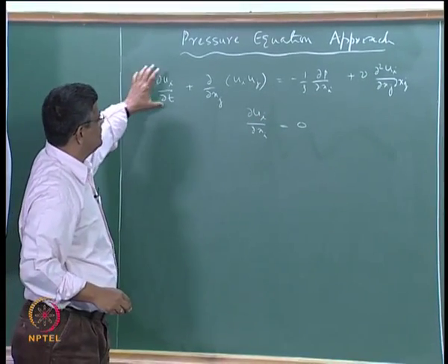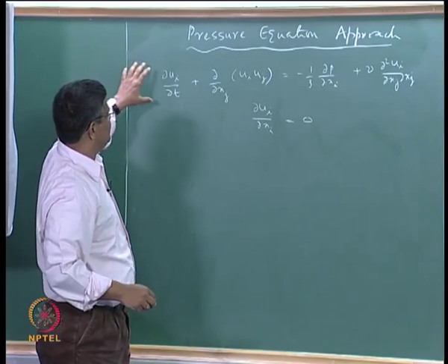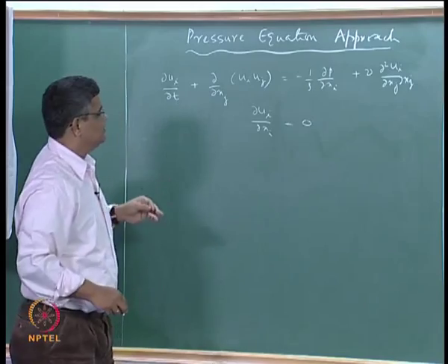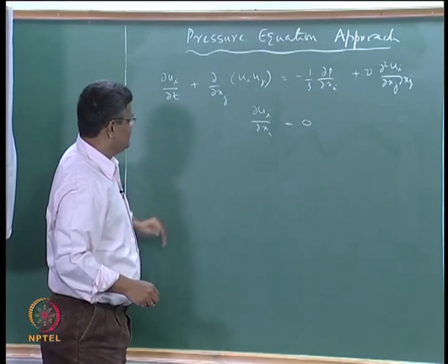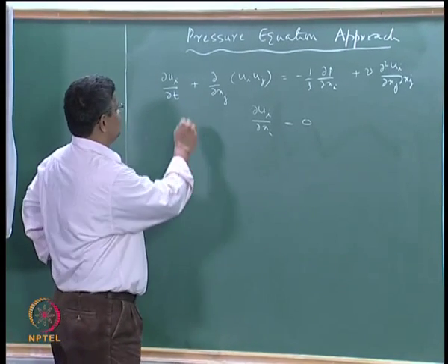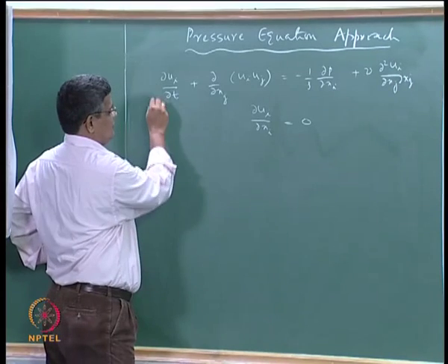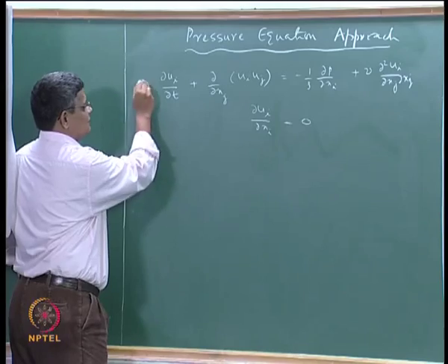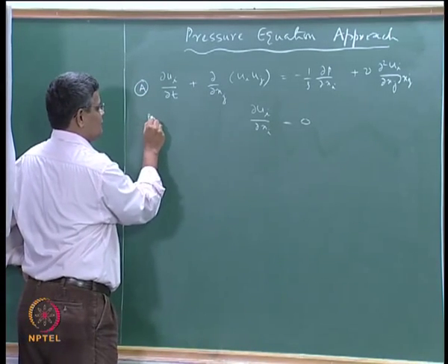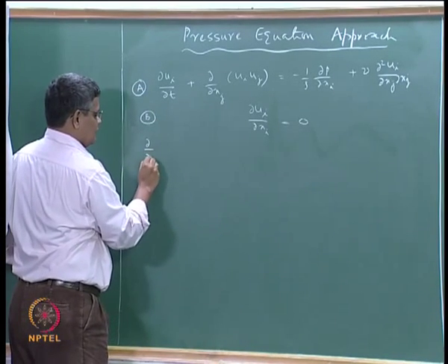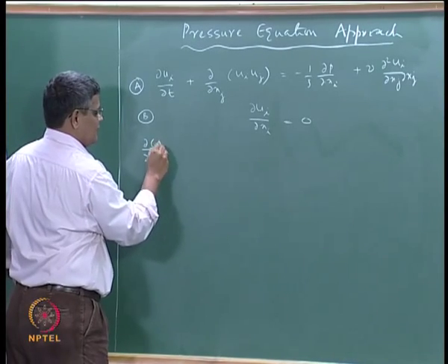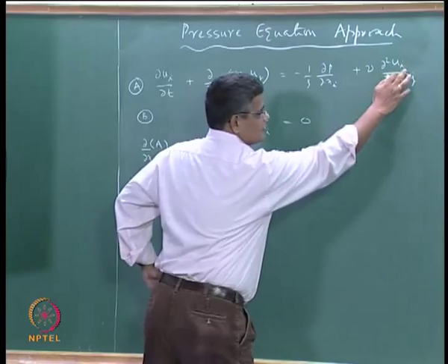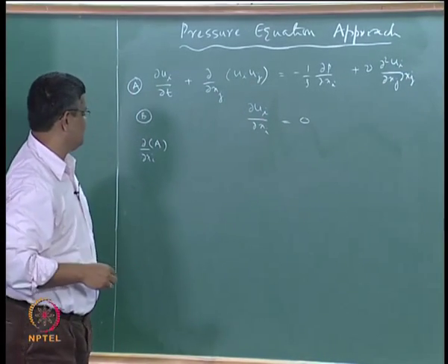And this is the generic scalar transport equation, and we can solve this provided we have the pressure. What we try to do is that we take the divergence of this. If you call this equation A and equation B here, then we take ∂/∂xi of A, given that in each term there is an i which is appearing here, so that we are effectively taking the divergence.